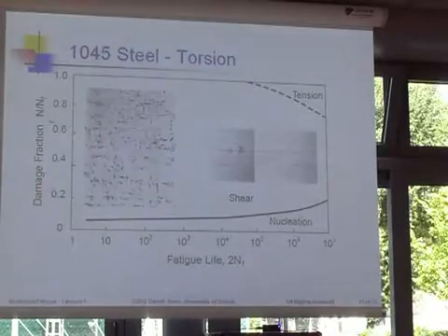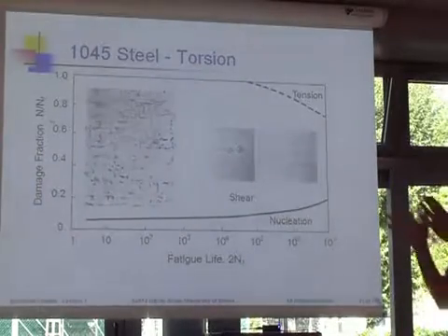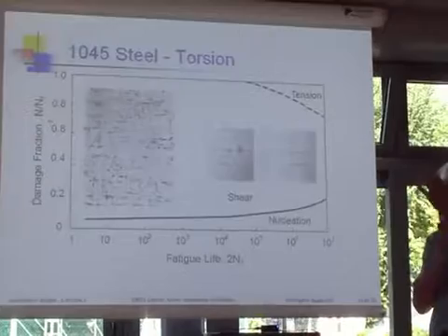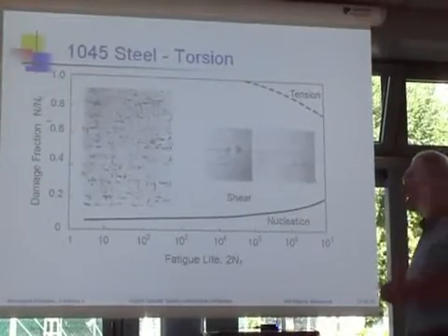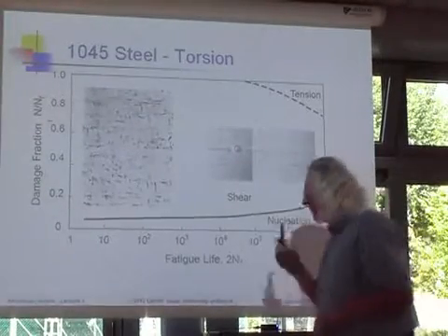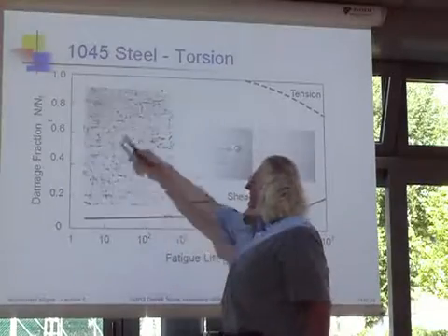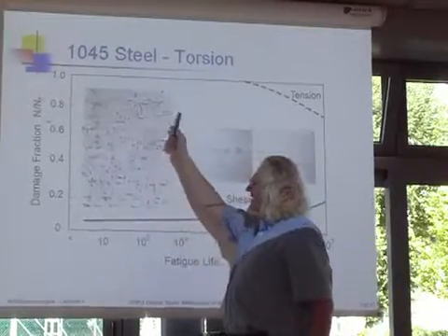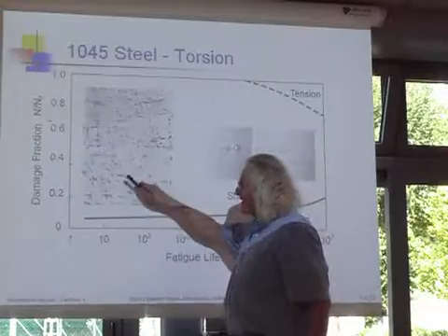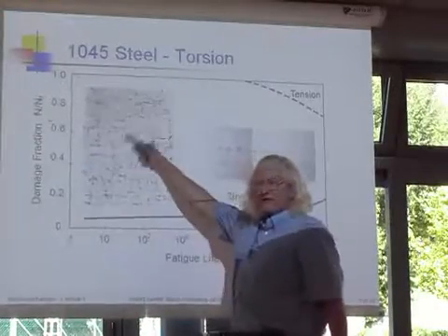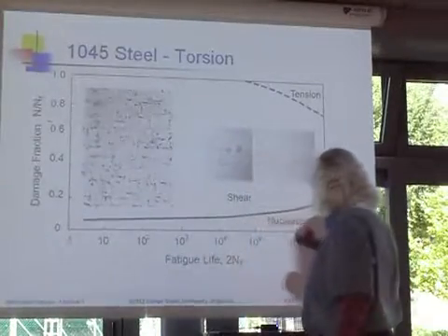They don't grow very fast because you have all of these stresses acting on a crack face. A lot of the modes are taken out by friction, and there's a couple of different modes in shear. When you have a lot of plastic strain, you just nucleate so much damage that this again tears like perforated paper. In fact, the end failure of this actually tears off at 45 degrees in the last cycles.